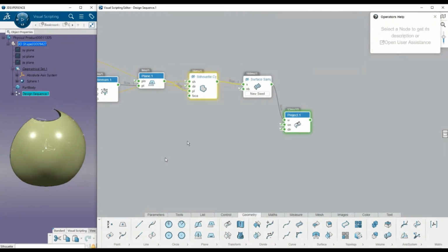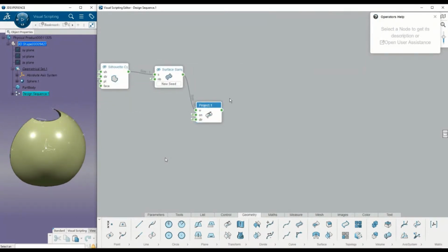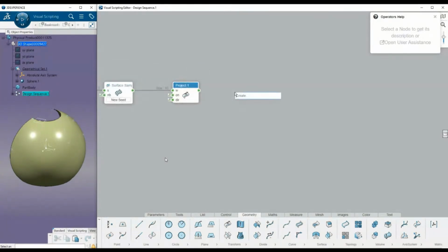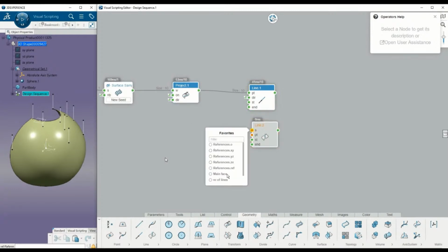The points are created on this flat surface. They are back projected to the sphere, and now we can of course deactivate elements that we don't need or hide them. And now you can see that these dots or points are created only on the upper part of the sphere, because we've been projecting them only in that top direction. Why did we do that? Simply because rain is dropping from the top and then will start to flow down.